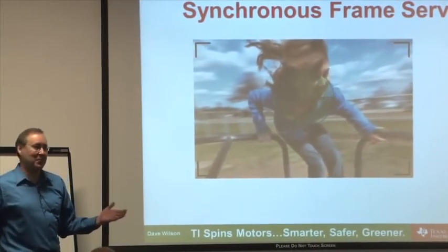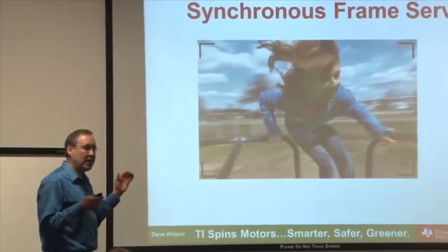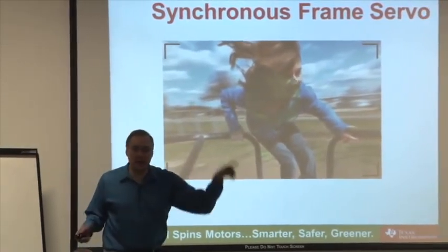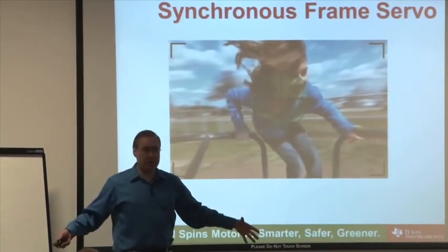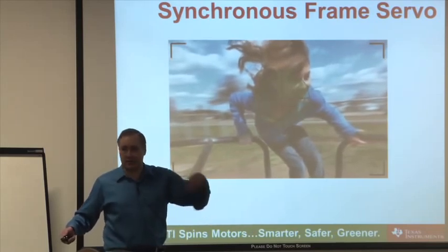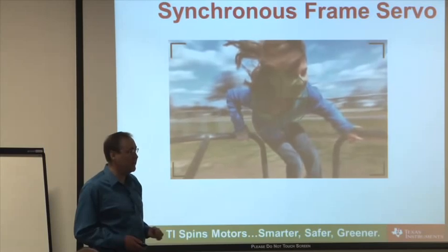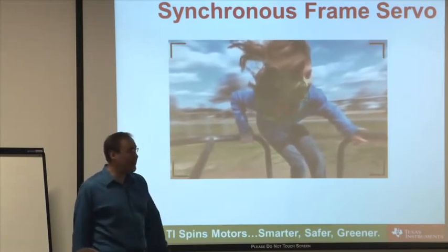Well, which way is the simpler way to do it, I guess, is my point. We would rather do the regulation of the current up on the rotating reference frame than trying to do it in the stationary reference frame that we were talking about before. Because as the motor would go faster and faster, we would generate faster and faster current sine waves that we'd have to regulate against. This way is a lot easier to do.